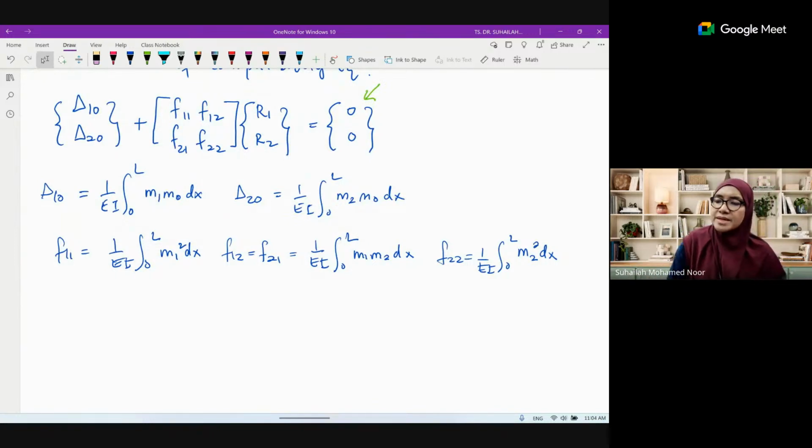Okay, actually you do not need to memorize these formulas because you have used them previously. We just adopt and adapt. The system is just like the real system and virtual system, but the labeling is different. The primary system has the same characteristic as the real system: a determinate structure with external loading.